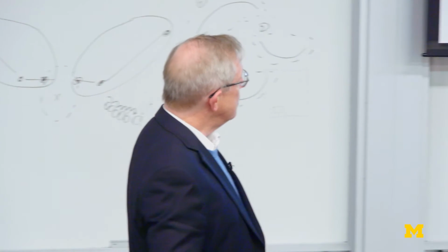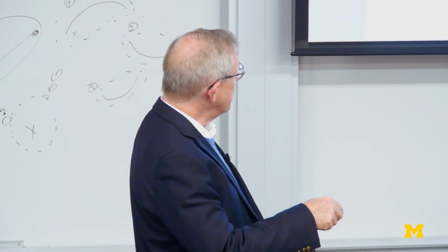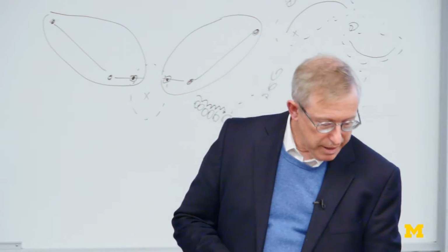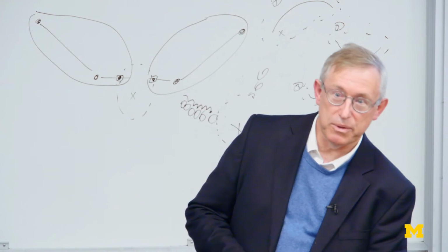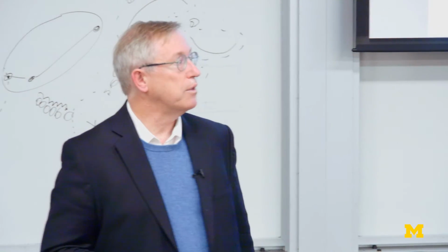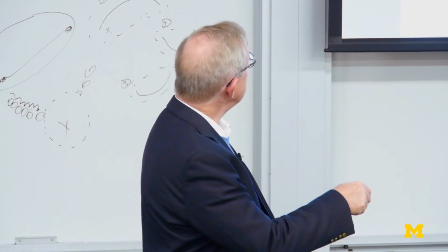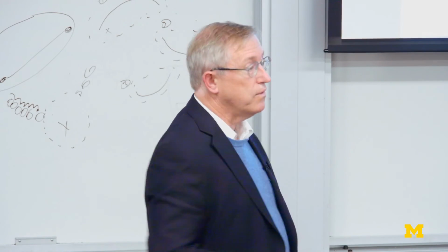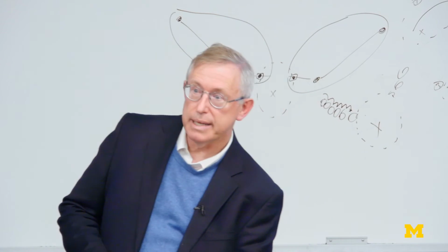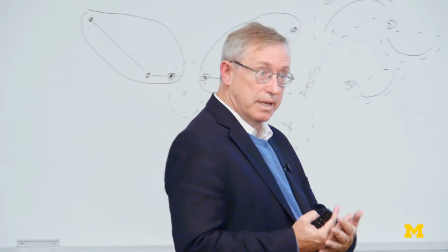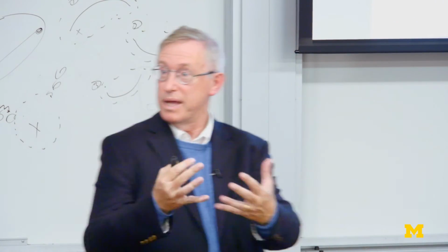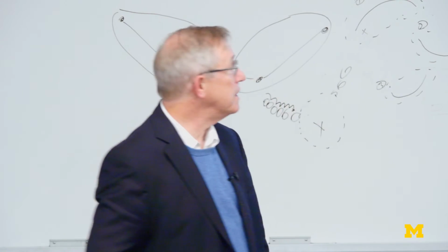The other thing that people often do, and always do in practice in fibers, is they put different users at different wavelengths. So instead of calling it FDM, the way wireless people do, they call it WDM in optics, wavelength division multiplexing. But it's the same concept. You have a user at channel 1, a different user at channel 2, a different user at channel 3, and so forth. So these users are linearly multiplexed. It's a linear superposition of wavelengths separated by some complex exponential modulation, right? It's the usual idea.